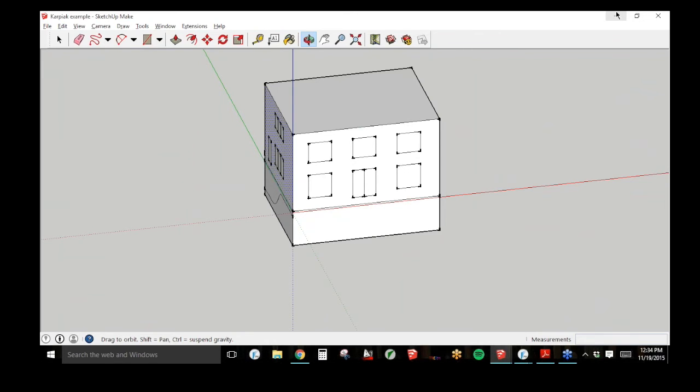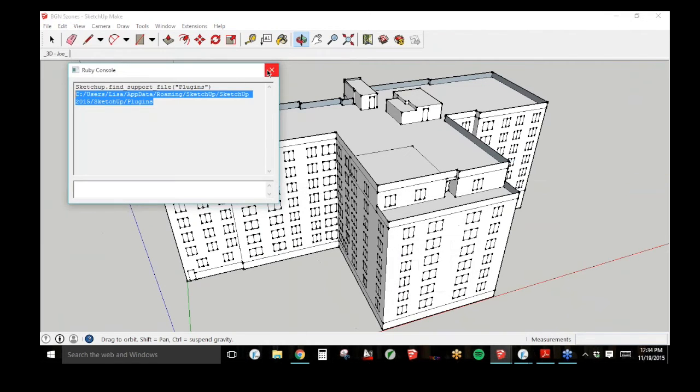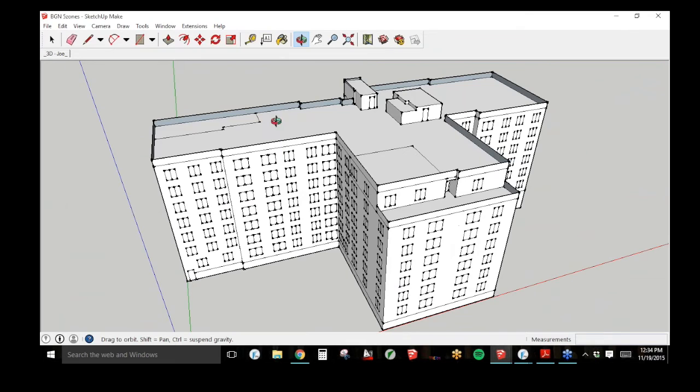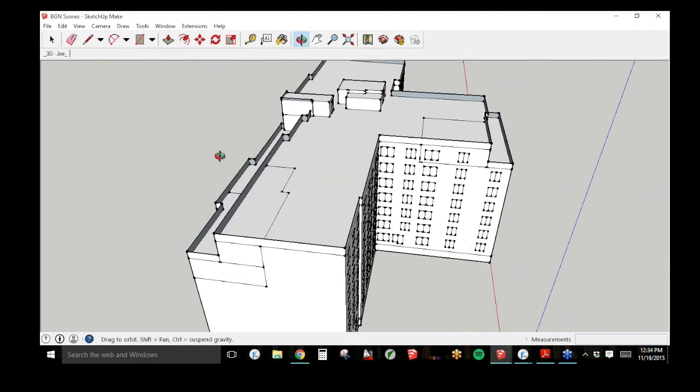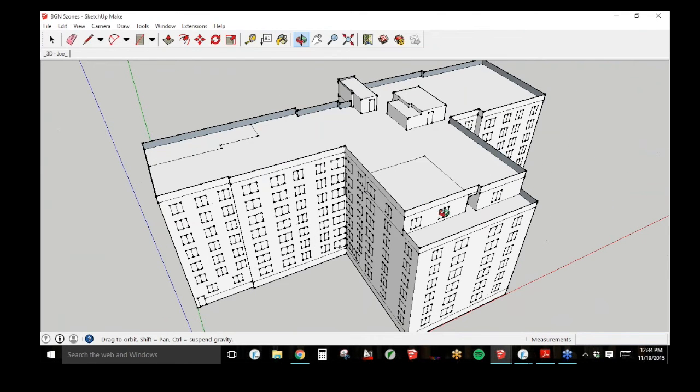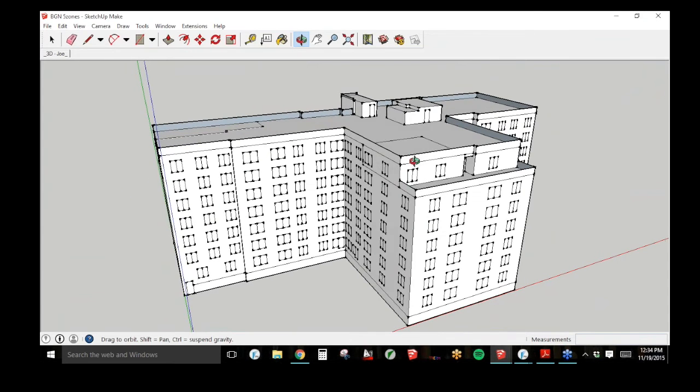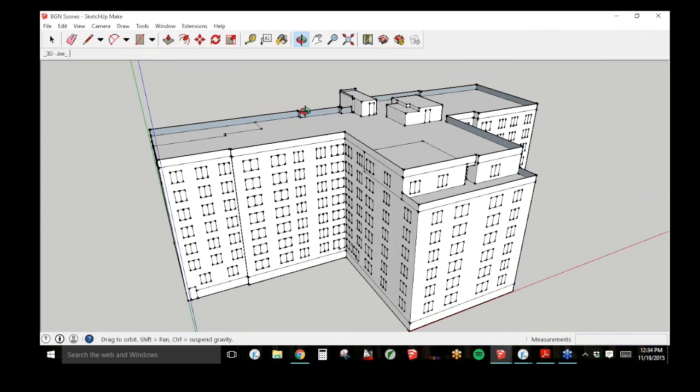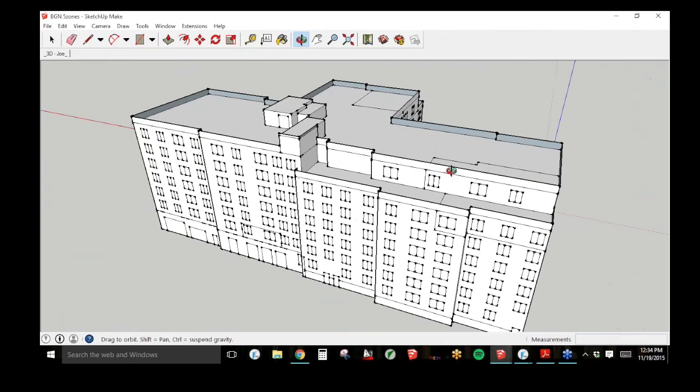So the next thing I wanted to show was a multi-zone model. Here we have a larger building where we zoned out a couple worst case units. The first thing we'll look at is this southwest corner unit. There's a lot of surface area and a lot of gains here, so we figured this might be a warm unit relative to the rest of the building. And then we have this colder unit, maybe only facing north, with a lot of envelope losses.